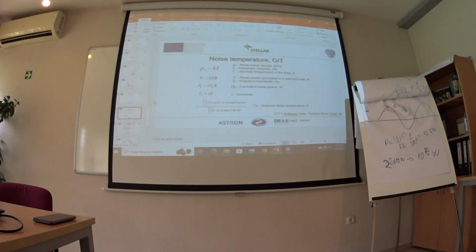So if you get a 50 ohm resistor and measure it with a highly precise voltmeter, you will see a voltage with a random shape waving around a specific value. And we wonder how to measure this value.